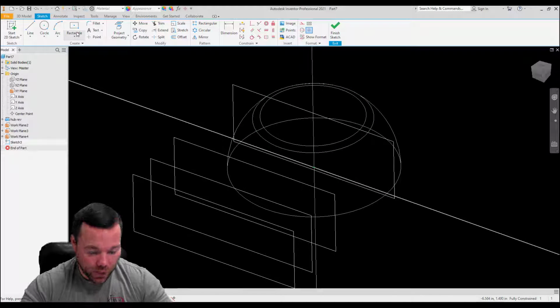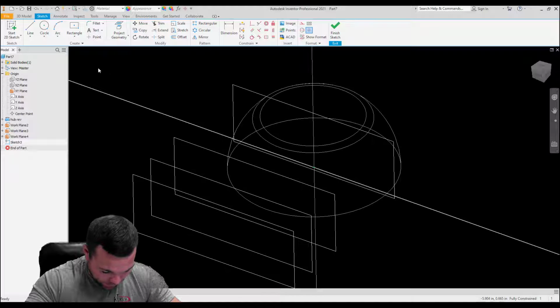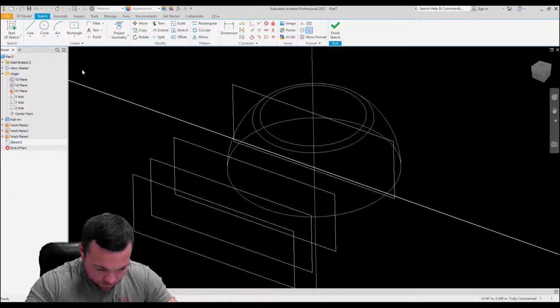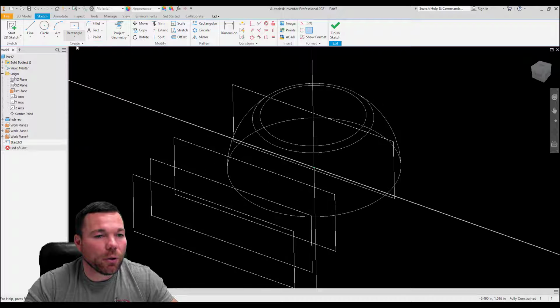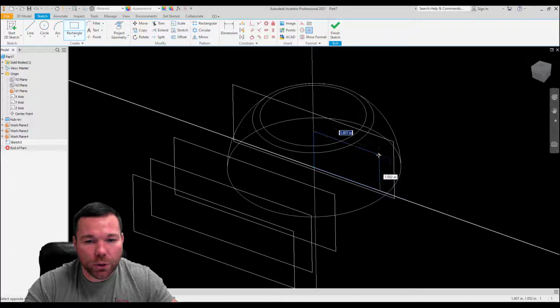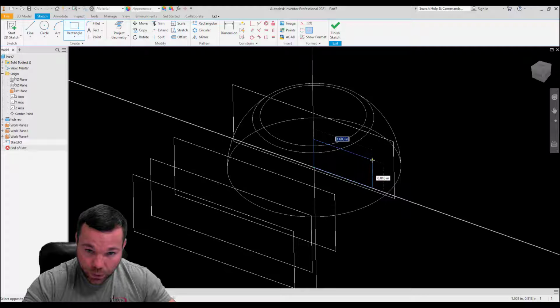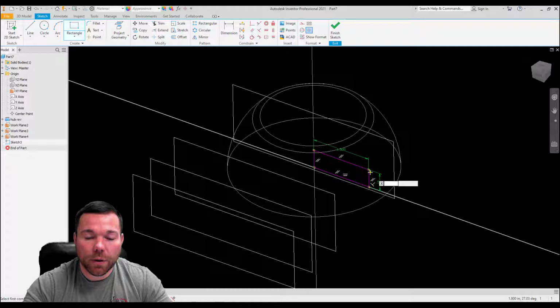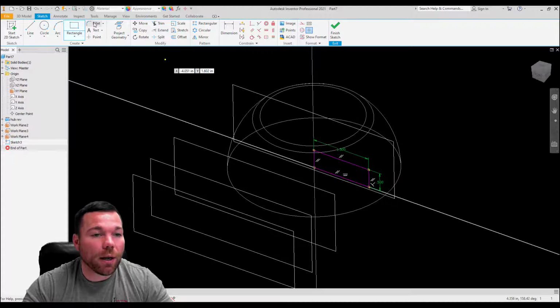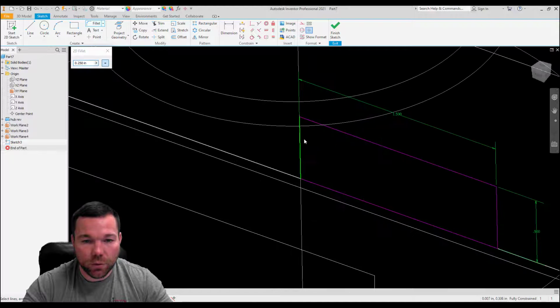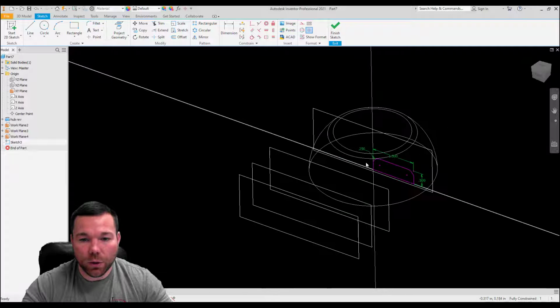Then we're going to go back to our sketch, and we're going to create a rectangle. It looks like it's right on the origin. That's what they're saying. So we're going to do a 2-point rectangle, start at the origin, and it's going to be 1.5 by 0.5. All right, and there is our rectangle. And then we're adding 1/4 inch radii to that. So click here and here, here and here, and we are good.